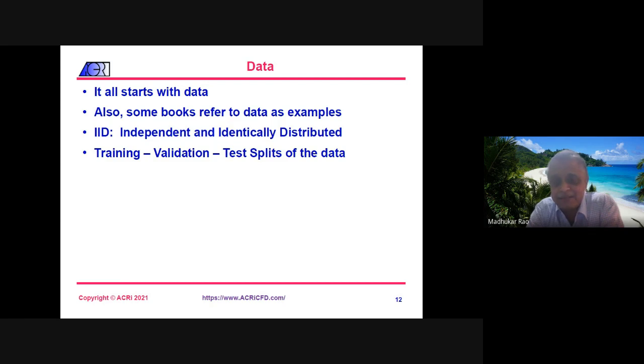So naturally, if your neural network is trained on one type of data, for example laminar flows only, then in the field, if it encounters a turbulent flow, it's not going to do a good job of predicting the values. So if you're training a neural network to predict both laminar and turbulent flow, your training examples should come from both laminar and turbulent flow.